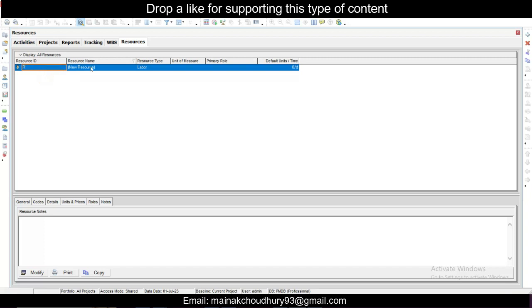So resource ID R, and resource name, suppose we go just let's go mason, and unit of measurement and default unit primary rule, this is done. And right click and just click on add another resource here. So this resource suppose will be R1, and this resource name will be suppose helper. Okay, helper, which labor which helps the masons.